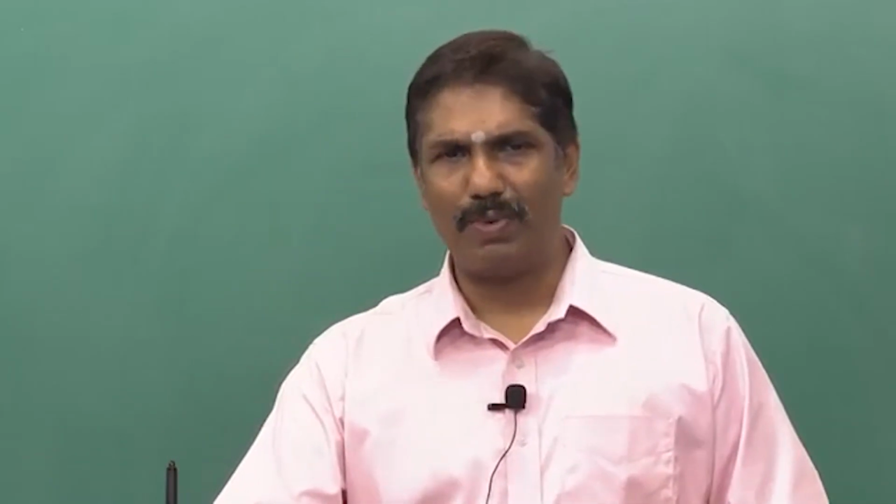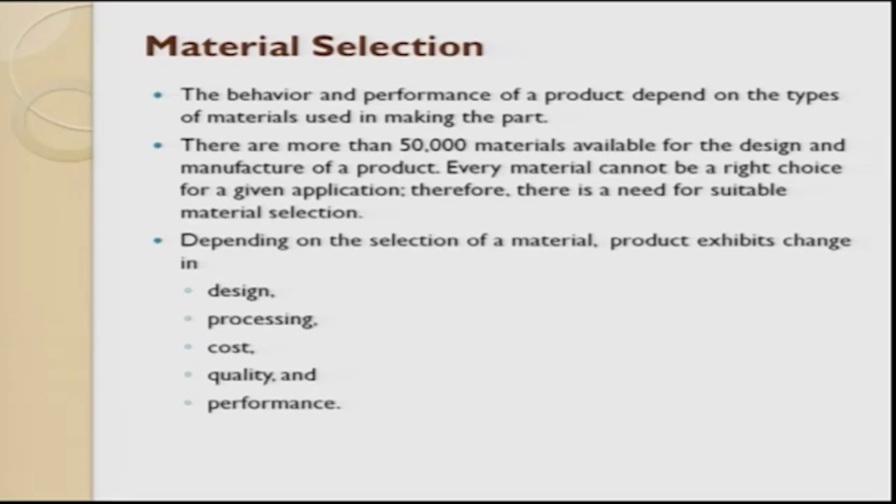The wood based and the steel based always have an environmental influence on the product, and over a period of time they both get deteriorated very fast. Both the steel chair as well as the wood chair can be folded. You can think of a folding process and then stacking it together. But the only thing is, when you work with steel or wood, the number of parts involved for assembling and making a chair is very high. So the assembly process is very high. The maintenance cost is also very high.